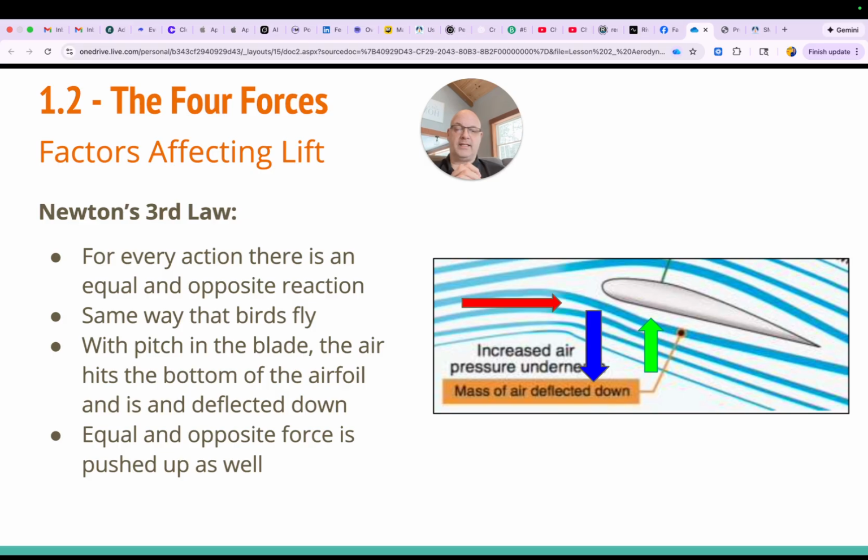And again, if you look at the two streams of blue, going over top and underneath the airfoil, think about a marching platoon of soldiers, and they all have to stay together. Well, those traveling on the bottom don't have to travel as far as the ones on the top. So the people going on top need to go faster in order to catch up on the back end. To do that, you start creating a pressure differential. Of course, you also have the angle of attack in a way that when the wind hits it is automatically deflected. So that helps with lift.